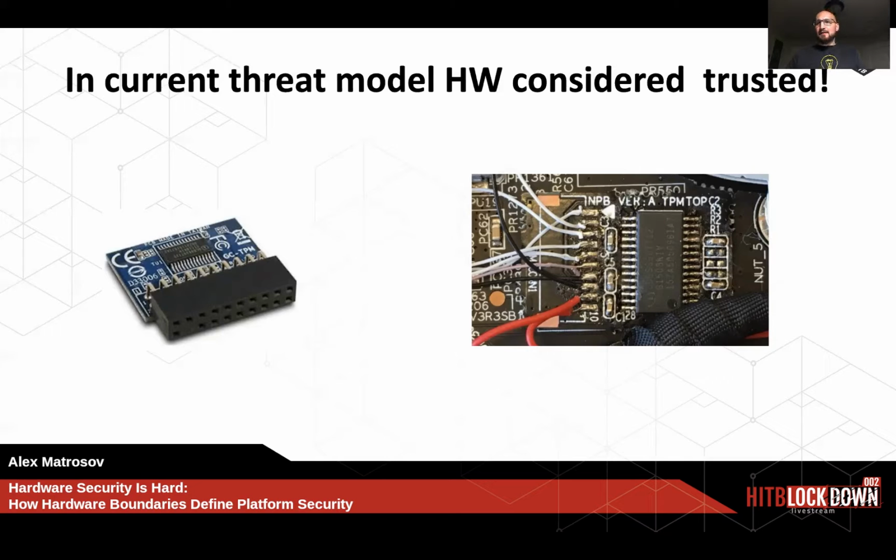And there was brilliant research from Jeremy Boone about a TPM interposer, and Trammell Hudson did something not the same, a different way, but also interposing TPM signals by soldering direct wires onto the chip. And you can see this in the picture. And a lot of server boards actually have a separate TPM, which is just connected in a slot. You can see it on the left side of the slide, which is also hard to consider a trusted root of trust, right?